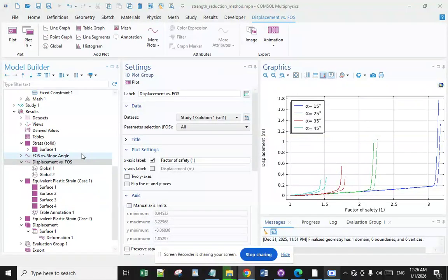Unlike the limit equilibrium approach, the strength reduction method can be readily operationalized by automatically identifying the sliding surface. In geological engineering, analytical and empirical methods are employed to evaluate the safety factor of soil or rock material depending on design requirements and engineering characteristics.